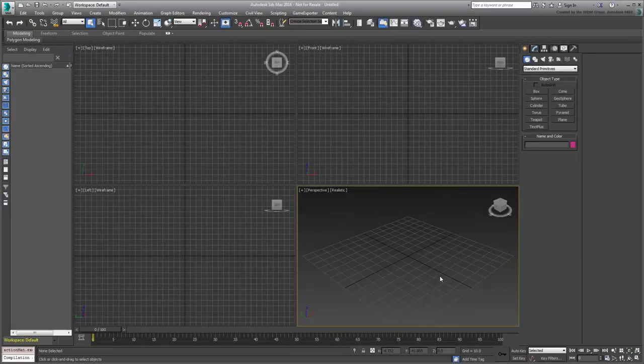In this movie, you'll learn about various ways to animate text created with the TextPlus feature. TextPlus is relatively new to 3ds Max and can only be used in 3ds Max 2016 Extension 1 or newer. Using TextPlus in combination with animation presets, you can create and reuse interesting animations on words, paragraphs, or letters.